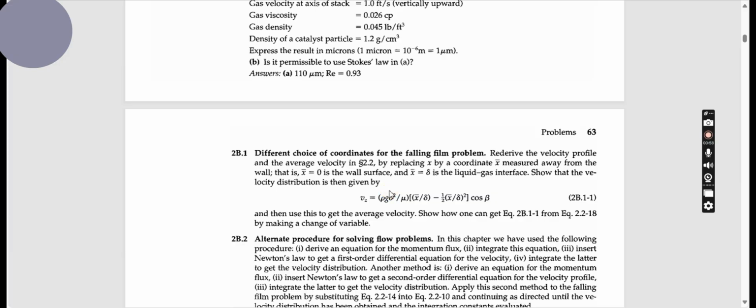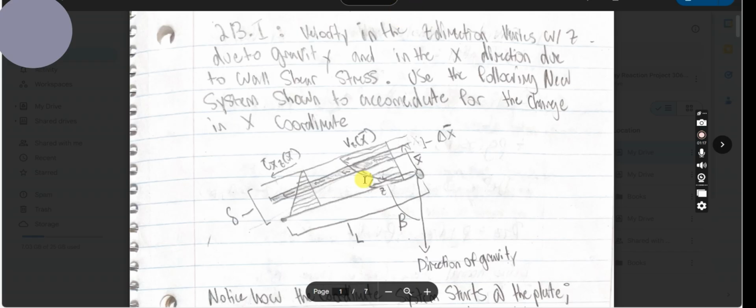And you'll see a mistake that I made. I defined a momentum z flux, and that would give you a differential pressure. Obviously, there's no pressure in the expression, so that was wrong, because the top of the liquid is exposed to air, so there's no differential pressure from the bottom to the top. If this was a pipe with walls surrounding the liquid, there would be a differential pressure, but since it's not a pipe, that doesn't exist.